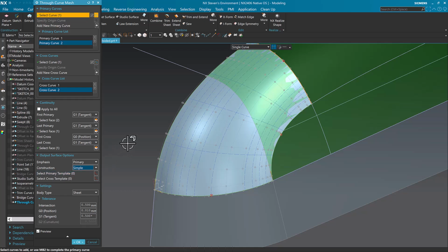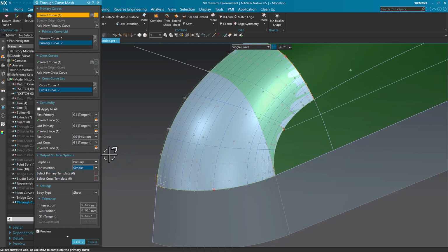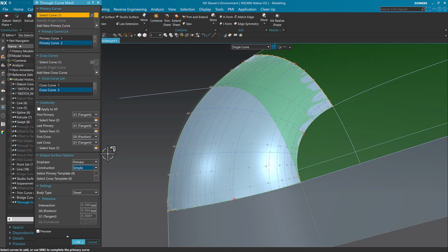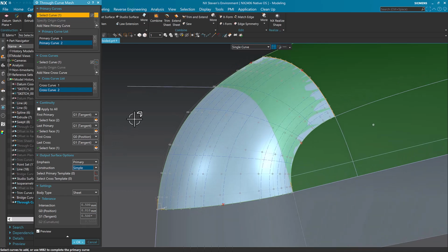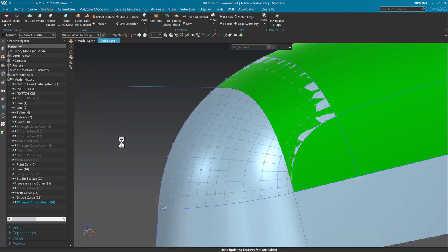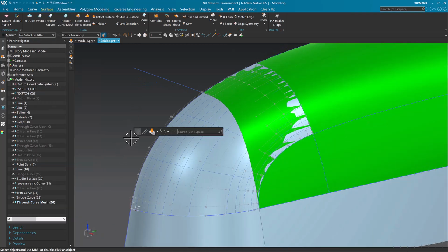If I have templates, I may be able to use a template, but I don't want to do that because it'll start really breaking away tangencies, and in this case, I can't do that, okay? But by futzing around in here a little bit, I'm able to, as you can see, get a slightly simpler, well, I wouldn't say slightly, it's a fairly big change as far as the level of complexity in the surface, okay? Now, I'm going to go ahead and trim my sheet.